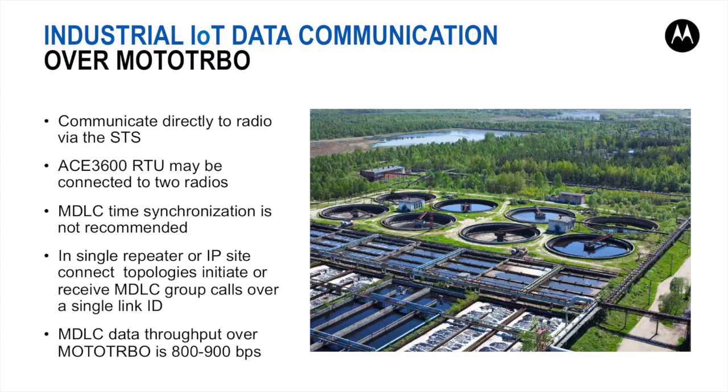A 3600 RTU may be connected to two radios provided they have different local IP addresses. The MDLC time synchronization is not recommended due to long delays added by the radio or repeater, and NTP is not supported either, as it is not an IP-based communication.